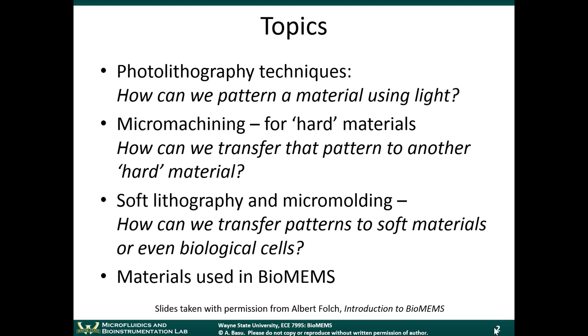And more recently, we're not going to talk about that in this module, but there are paper-based microfluidic devices which can decrease the cost to less than a penny. Okay, so different materials are used in micromachining. There's more of an emphasis on soft materials like plastics and PDMS in BioMEMS because, as we talked about earlier, often the devices have to be disposable. Diagnostic devices, for example, are often disposable. We don't want to reuse them. And in this module, we're also going to be talking about different types of materials used in BioMEMS.